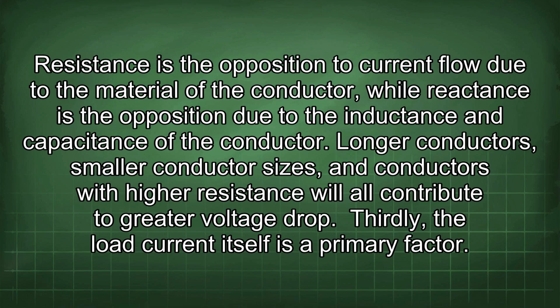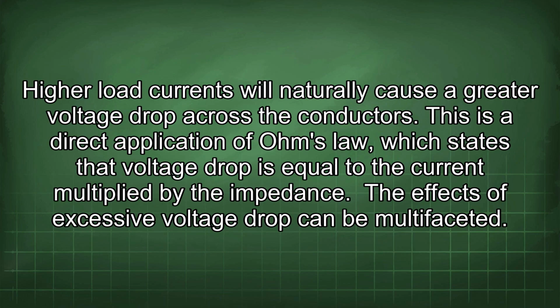Thirdly, the load current itself is a primary factor. Higher load currents will naturally cause a greater voltage drop across the conductors. This is a direct application of Ohm's law, which states that voltage drop is equal to the current multiplied by the impedance. The effects of excessive voltage drop can be multifaceted.